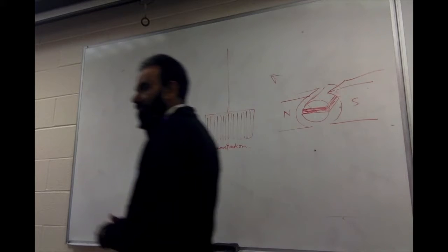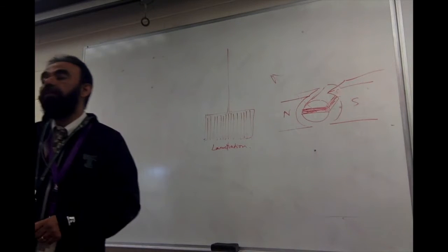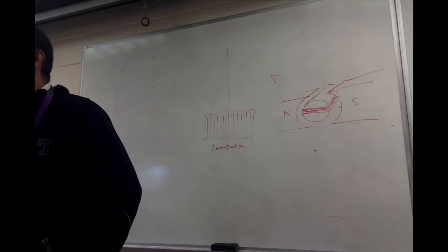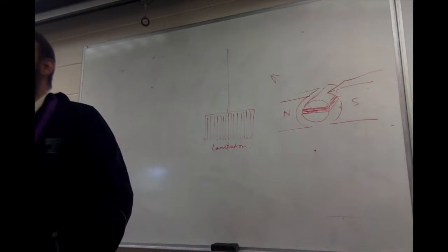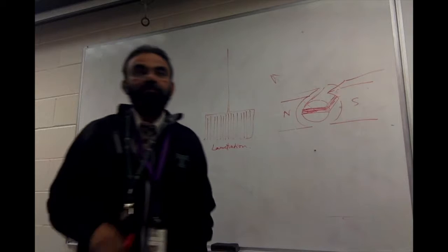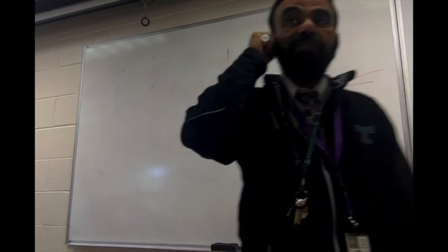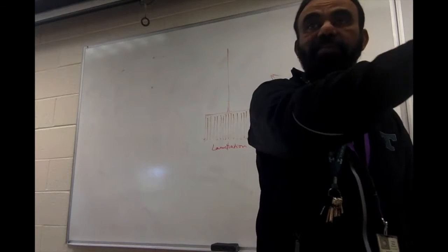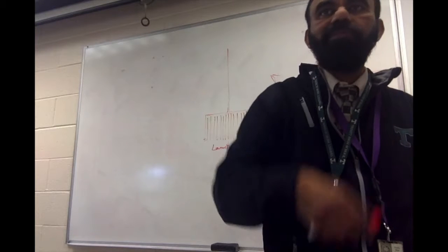You see it? So that coil won't have lamination? Say it again? That will not have any lamination? No. We don't want lamination there because we want the critical damping. Whereas in that one, we need that lamination because eddy current is something that can resist the motor.